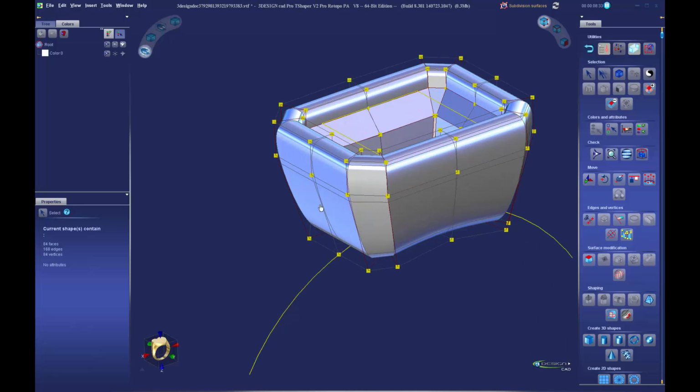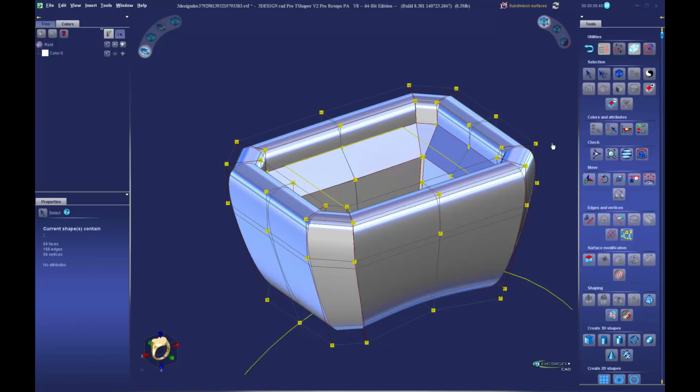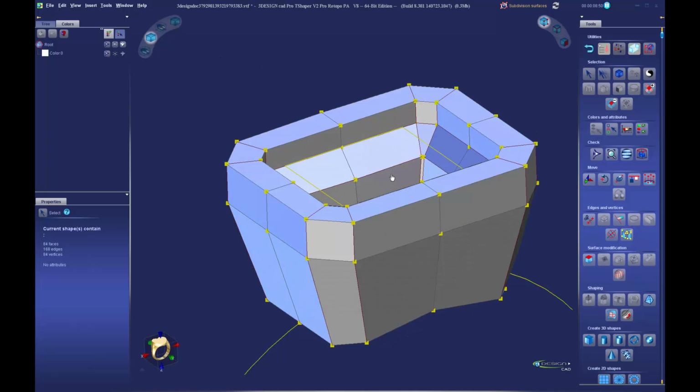You'll notice that it still kind of bulges. Don't really have straight outside parts, and that's because we don't have enough geometry constraining the top and bottom of the shape. So to fix that, we can add some more splits. So I'm going to go into box mode so we can see clearly which edges we're splitting.